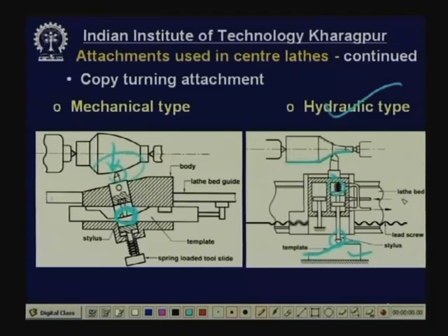Now, when high pressure oil comes through this and enters, it tends to enter into this, and there are two ports here, not shown over here. So, this oil cannot enter into this chamber nor into this chamber. This whole saddle is moving in this direction continuously with the help of this lead screw. So long as this remains on the flat surface, there will be no movement in the stylus, these two ports will not open, and the cutting tool will also follow a straight path.